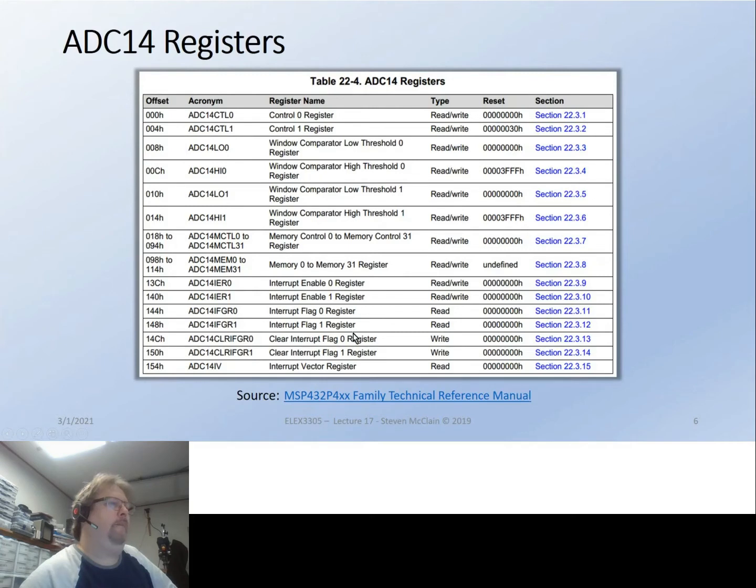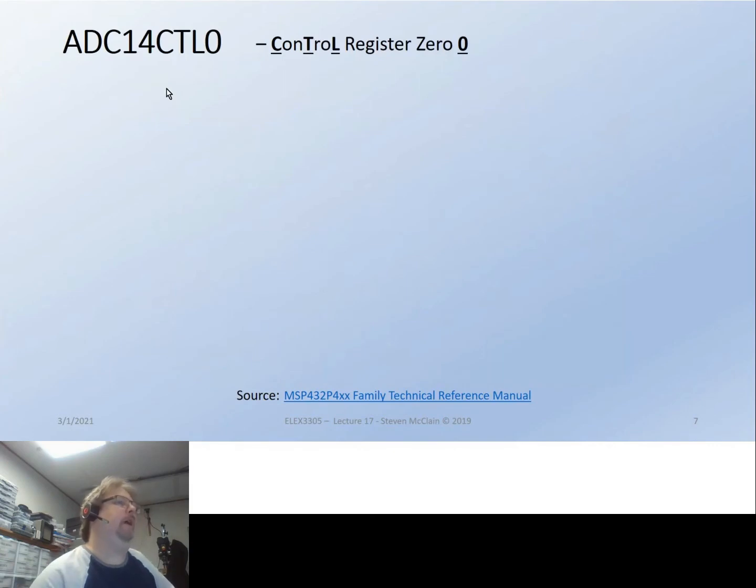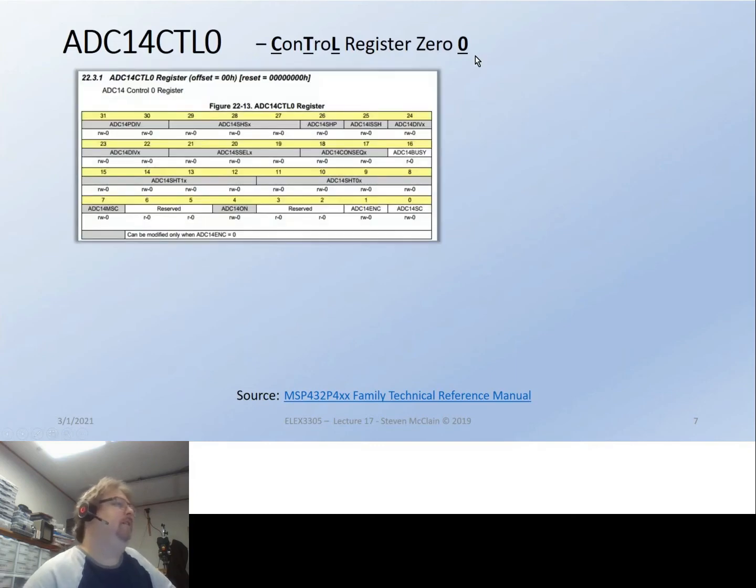Sorry, Stephen. So each one of these registers is just 16 bits, right? That's correct. Okay, so the control 0 and 1 are tandem, like you have to program them together. Well, they're two different registers. You see the offset here. So offset 0, this is like 4 bytes away from it. Oh, so this is actually a 32-bit register. Okay, gotcha. So they're 32s. Okay, control 0. And then a little mnemonic here. Look at that. See, it's 32 bits. Wow. Just to make it extra hard.